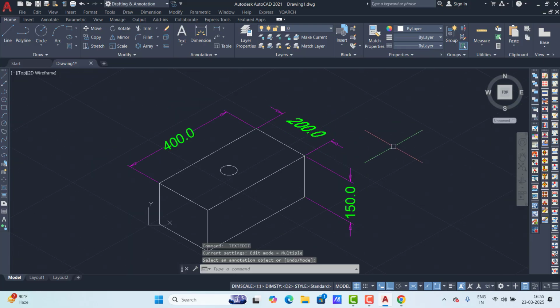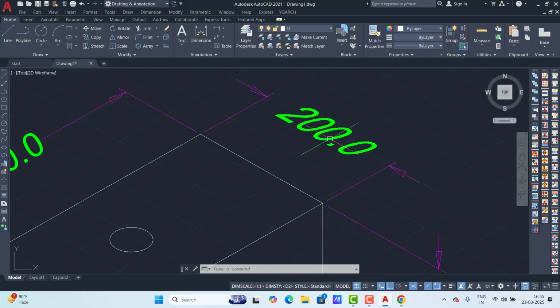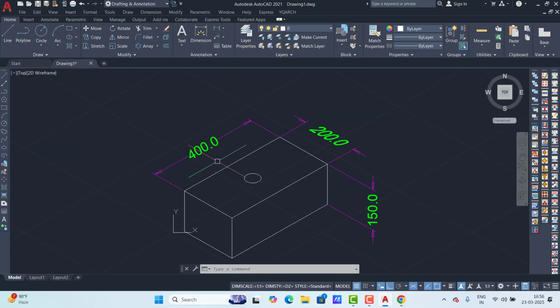Okay. Now we have to make one small circle, that is radius 3. So just select the circle, and first we have to make this center line 15.7. So again C enter, select this one, 15.7. Just make C enter and make one circle here with radius 3. Use your polar array, select this one, give the center here, enter 8 numbers. Finish.